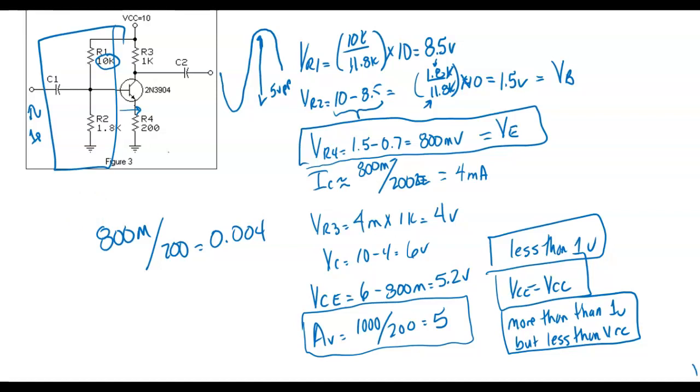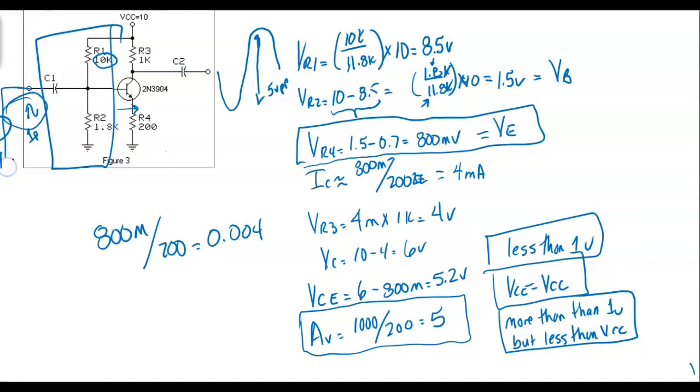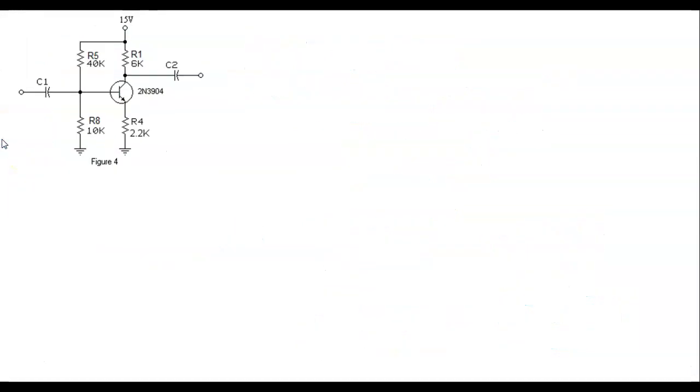But that's a fairly good example. And y'all understand why the input and output are 180 degrees out of phase, because we're taking our output across the transistor. So when the input goes positive, the transistor cuts on more, it drops less voltage, right? This is a characteristic of what we call a common emitter. When we say common, we're not talking about the DC common, we're talking about the AC common. And if I put the symbol for my AC signal over here, is it showing up there?